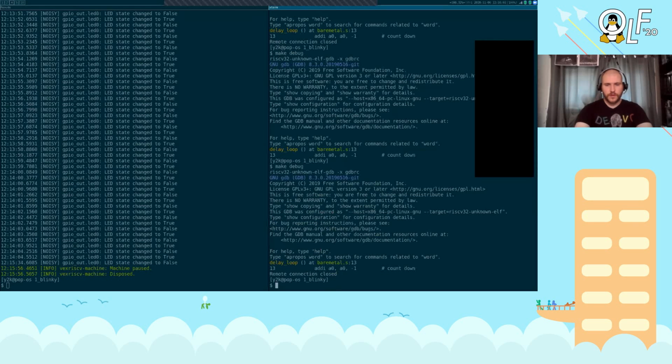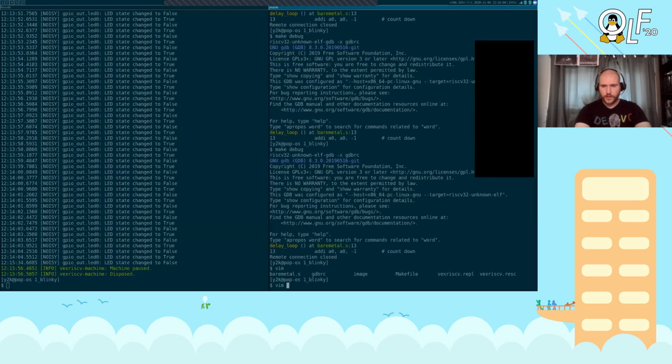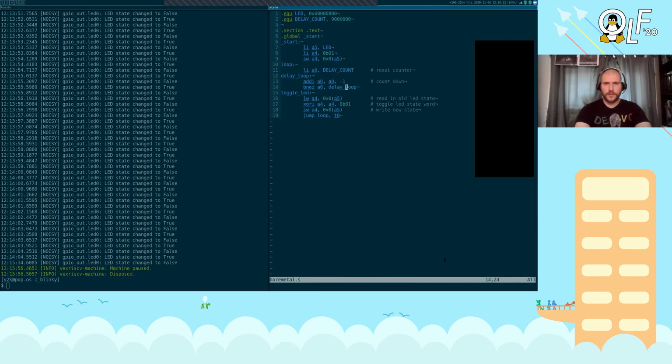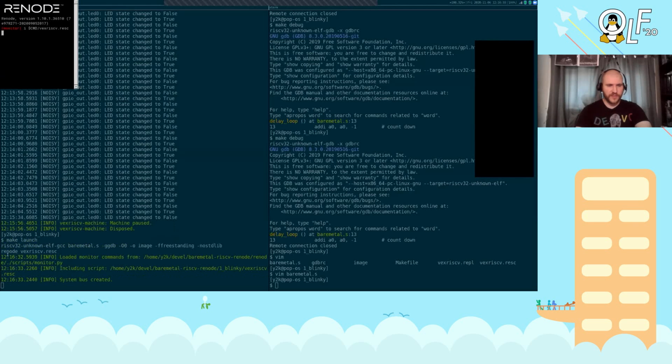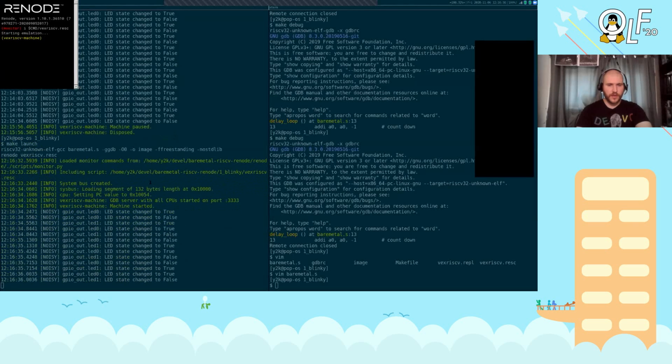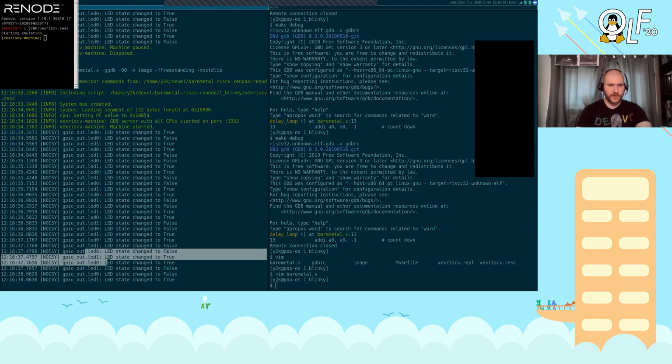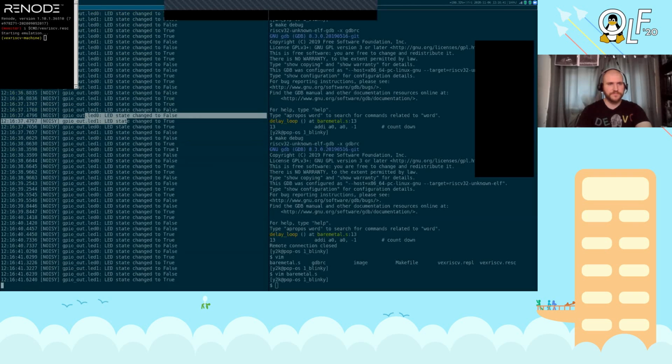And if I wanted to change that bit mask, come in here, and you can see where we've said how much to delay, but here's the mask. So I'm gonna just change this to a 1. So now it's masking both LEDs. And come over here, I can recompile. So it ran this RISC-V GCC Baremetal, and now you can see both LED 0 and LED 1 are both blinking alternately.